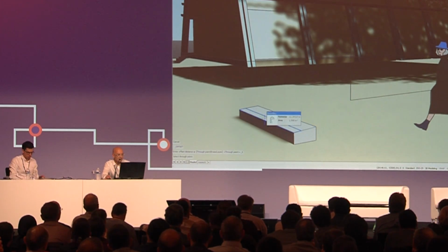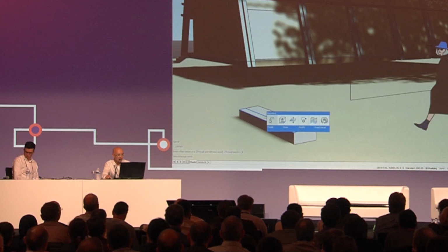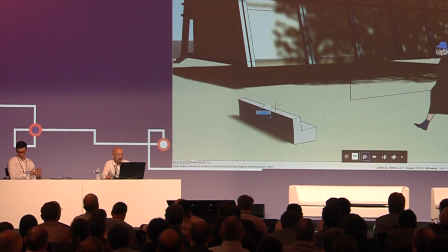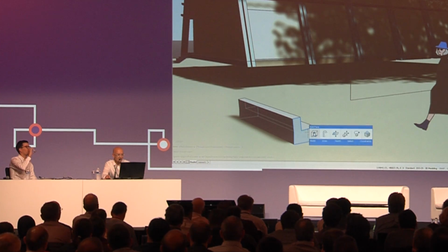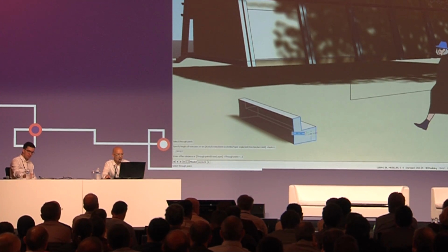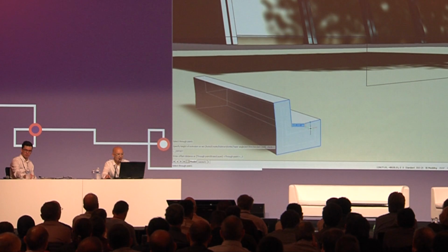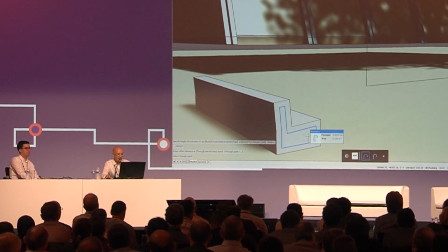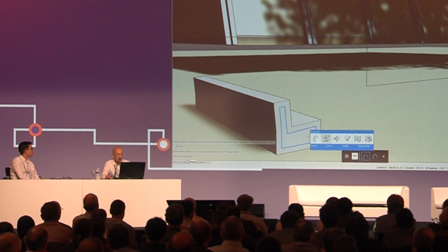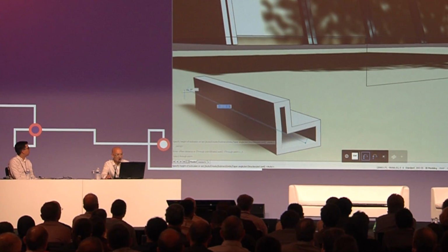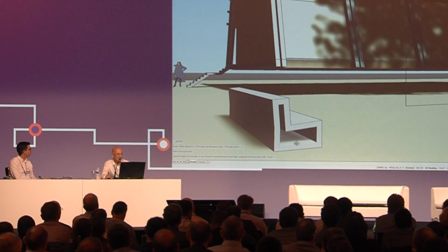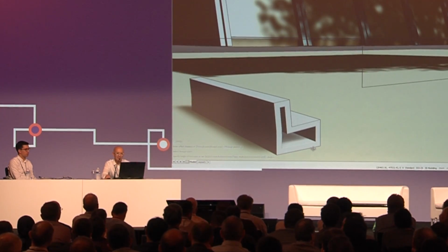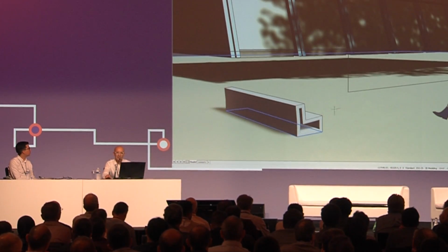It's a new way of drawing. Like here, the boundary is found. I can reuse that boundary. I can use that offset technique that you just saw. I can also use it on a face to offset here on this face. Yeah. I can use the extrude functionality in different ways. It automatically tends to get right at what you wanted to achieve there. So yes, you can model, no problem.